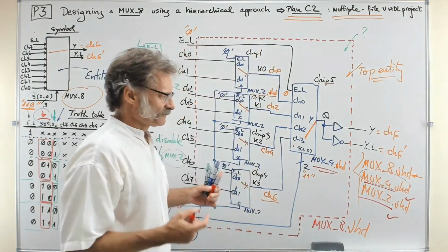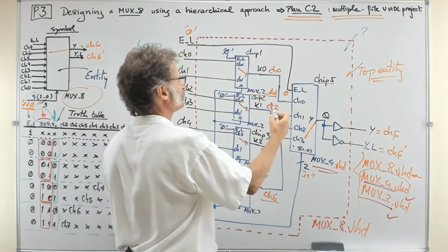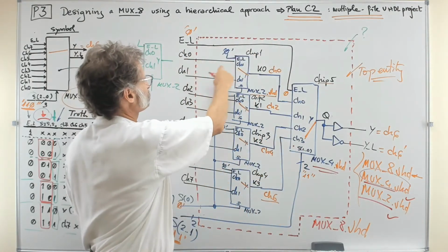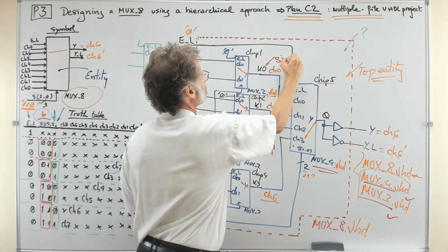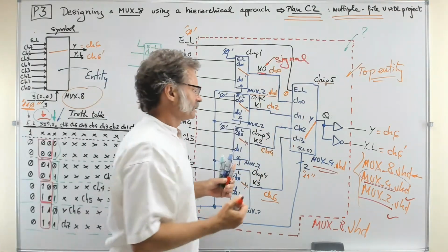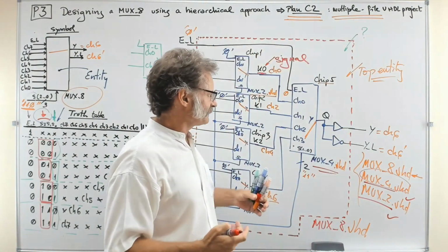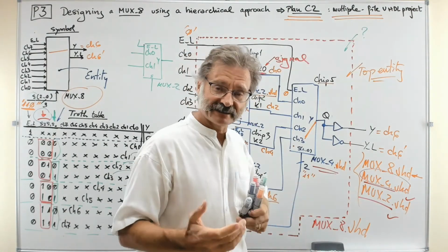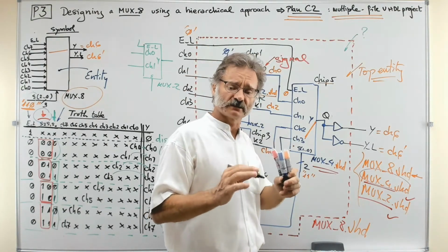So you see, first of all, find the components, name all the connections. I usually use different colors to do that job. The ports have a color, and then the internal signals, you see, this is a signal. This is very important. Every signal has to have a name. So do that job, and then leave the gates as they are to annotate them in the VHDL. But then there is the crucial question that I leave for you, so that you can think about it and you can watch the video. But you have the advantage that it's going to be all the time the same way.